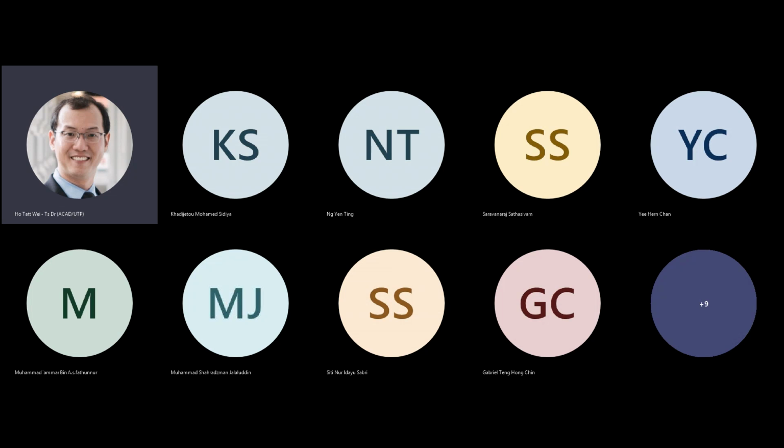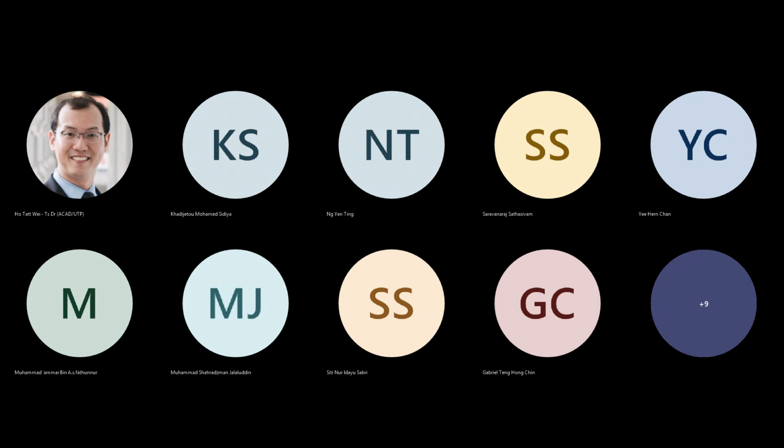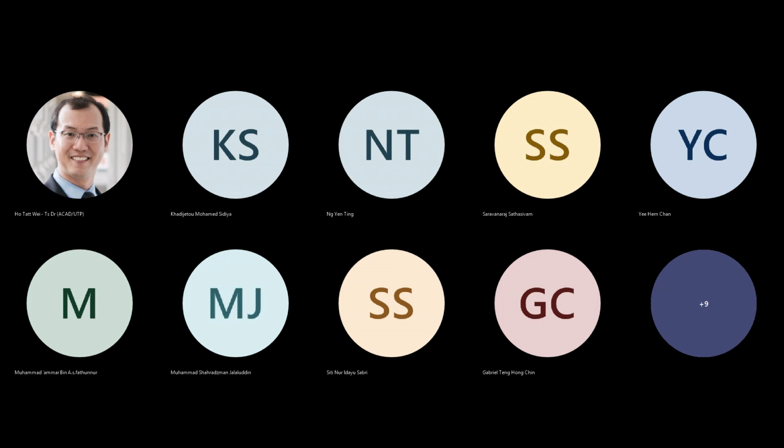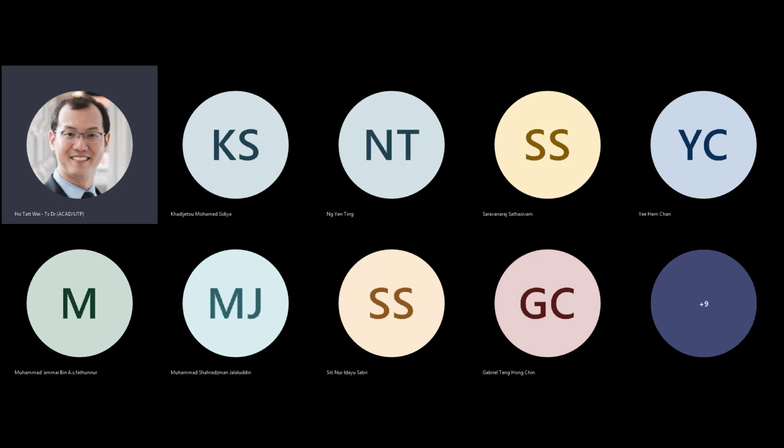It's a resistance. So I'm able, using this curve, this relationship here, which can actually be plotted as a curve, right? Over VDS, you get a curve that looks like this. A bunch of curves, right? And this is the curve at the value of maybe VGS equals 0.5 volts. This is VGS maybe equals 1 volt, VGS 2 volts and all that. But basically you get this curve, and the slope of this curve at this particular point or this particular point is the inverse of the resistance here.